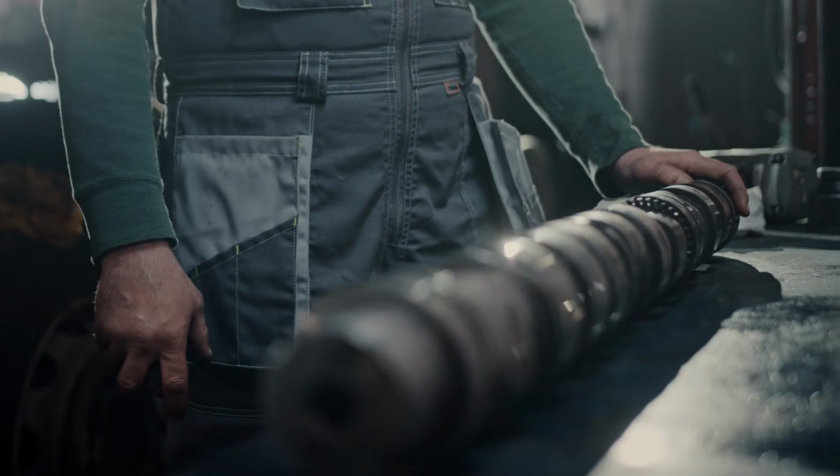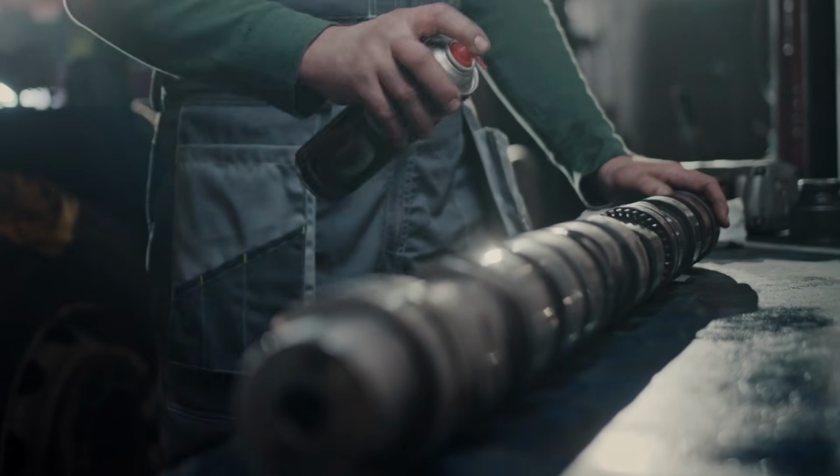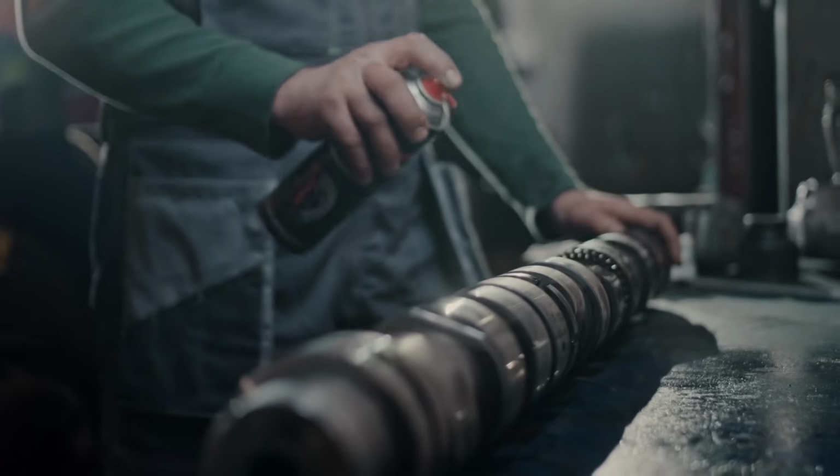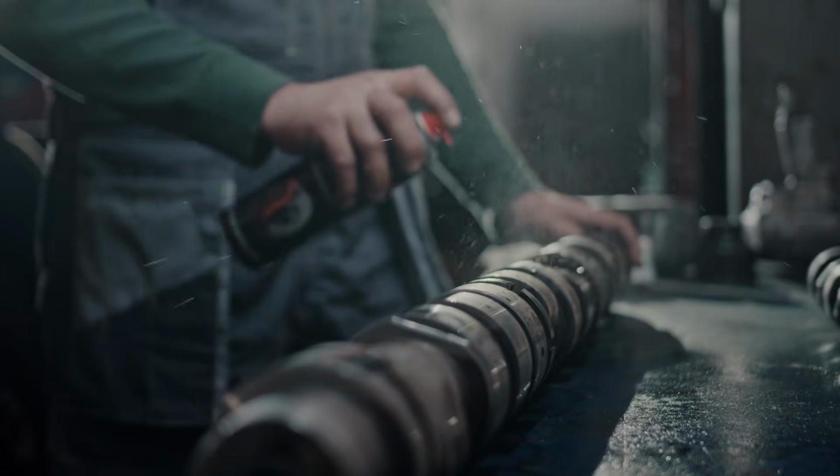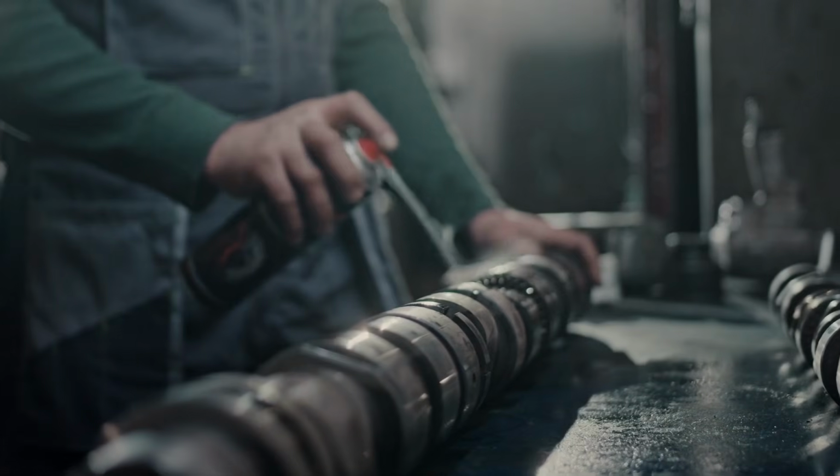If you've made it this far, write G50 above every G96 line. Use G97 for drilling, threading, and centerline work. That's the whole rule, and it keeps parts in the chuck.